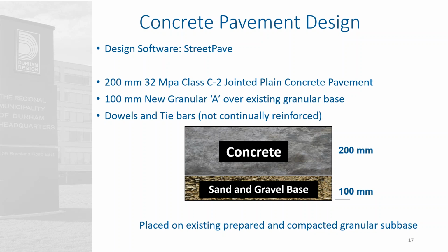That's placed over 100 millimeters of new granular A, which was placed on the existing granular base. So basically we excavated 300 millimeters of asphalt and granular, then compacted the base and placed our new granular A and concrete.